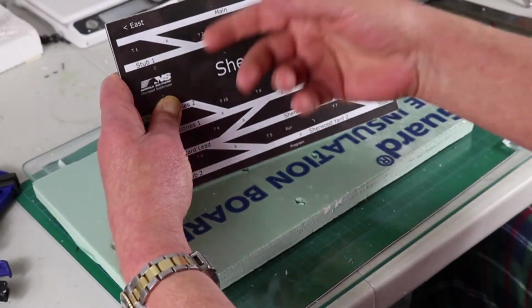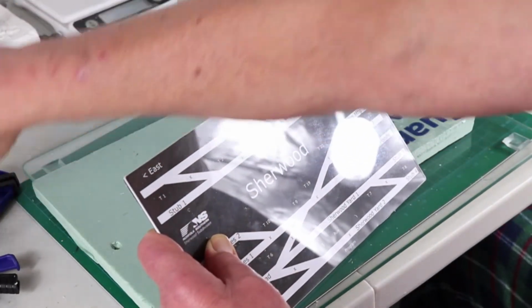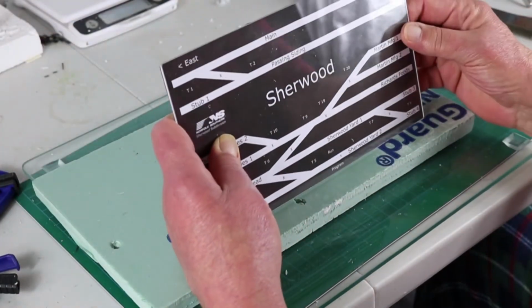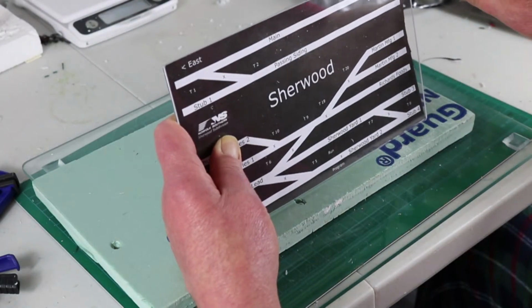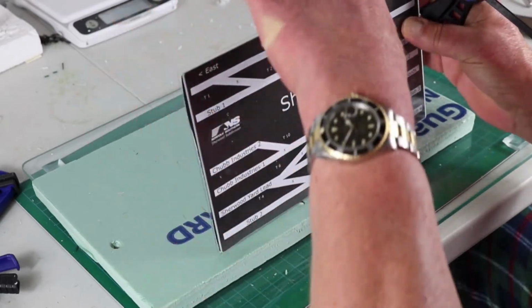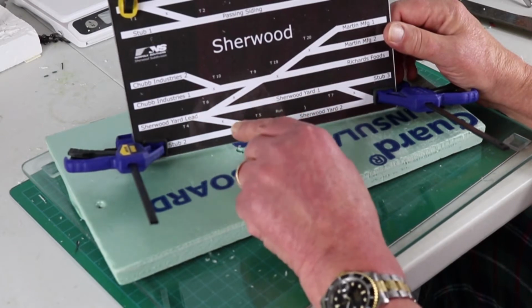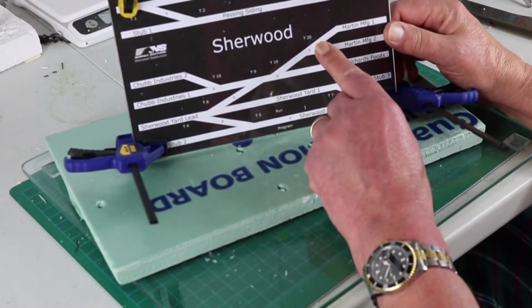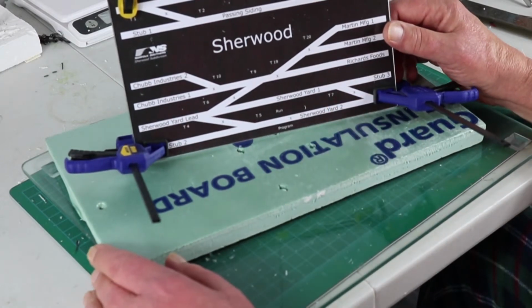Now don't worry about all that stuff that's underneath there, because we're going to remove this and clean it later on. And when we believe it's lined up properly, we will put a clamp on each corner. When I created the diagram, I put little marks, those X's, where the holes need to be drilled. So we're all set to go with drilling the holes.